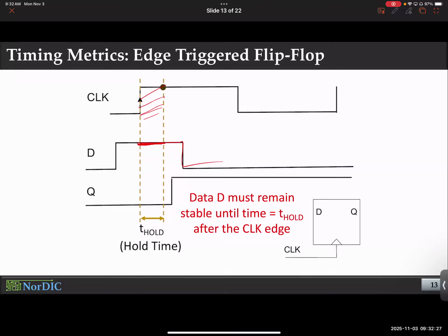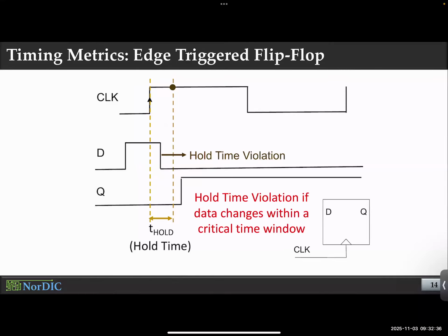All right. So notice, after the clock edge appears, your data remains stable for a certain amount of time. That is the hold time. Okay. Now, let me show you a violation of the hold time. I hope you can detect this easily. And we are taking simple examples here to let you settle down. So this is your hold time window. Within this time, you don't want any changes to the input either. What happened here? Is there any problem that you see? Do you see any problem here, folks? During the hold time window, your data started changing. You don't want that.